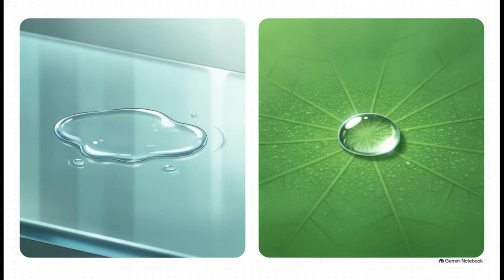The liquid just spreads out, like you'd see on a piece of glass or some cotton. But if theta is greater than 90 degrees, the surface is hydrophobic, water-fearing. Think of polymers or rubber. A brilliant natural example of this is the lotus leaf. It has these incredible microscopic patterns that make it super hydrophobic, giving it a contact angle of over 150 degrees. Water forms perfect spheres and just rolls right off, completely clearing away dirt as it goes.